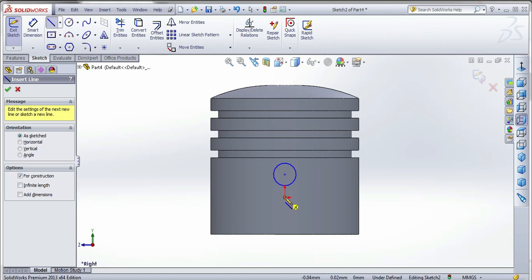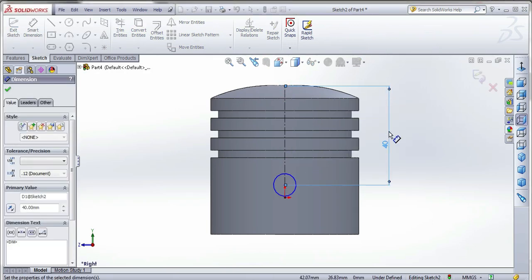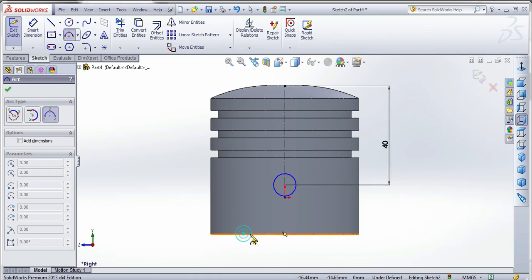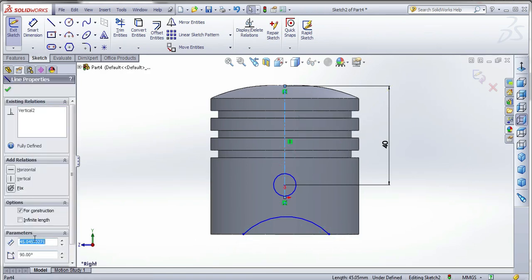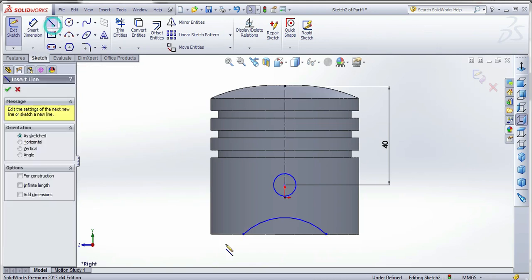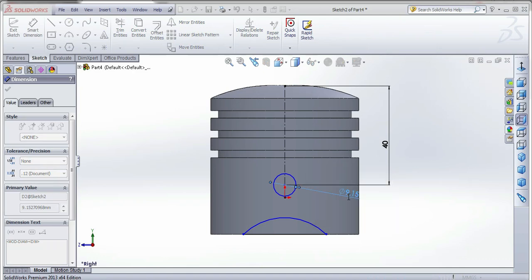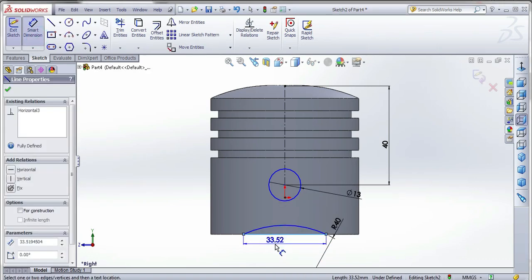Draw the center line to measure the dimension from the top to the circle center. And for the bottom cut section, you can draw the cut section, maybe select a 3-point arc. You can make it symmetric, this point and the center one. Close the arc. We are going to measure the dimension. Radius of this, the bottom length is 40.